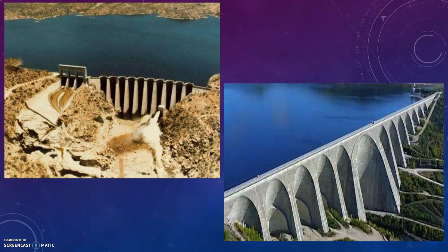Let us discuss some of the advantages of buttress dam. A buttress dam is less massive than a gravity dam. Hence, the foundation pressures are less in the case of buttress dam, and it can be constructed even on weak foundations on which the gravity dam cannot be supported.